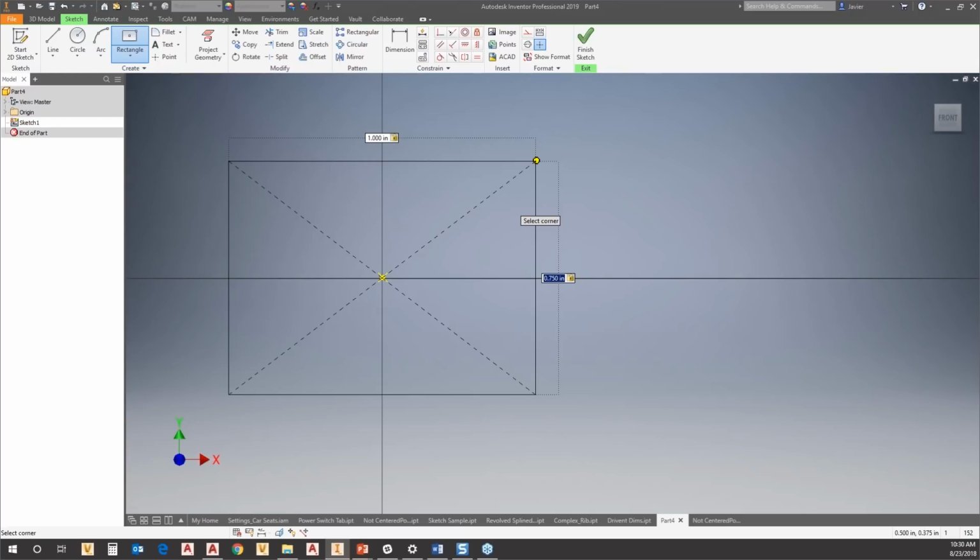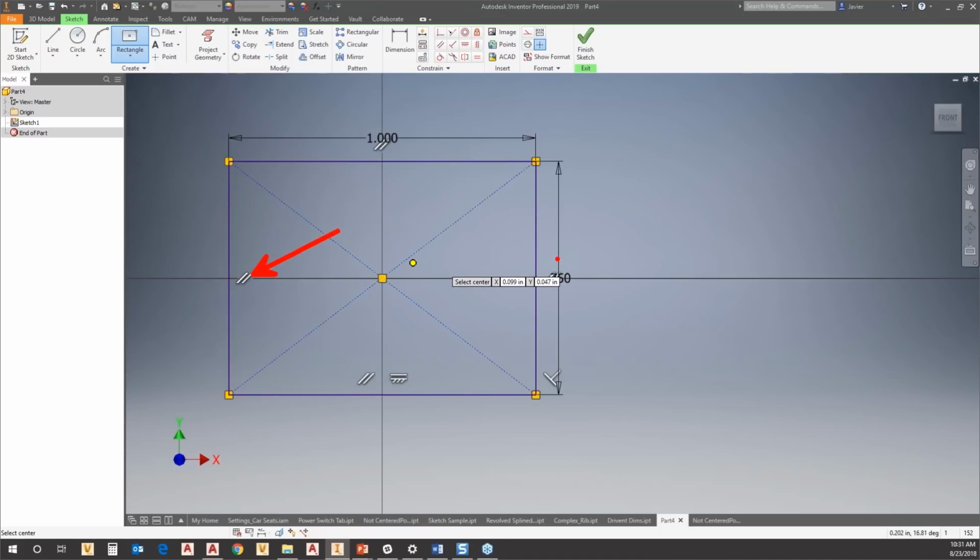In addition, right, we also use the rectangle command. So the rectangle command is going to automatically start putting in constraints relative to rectangles. So once I'm done, you can see some of those constraints. There's a parallel constraint that got added, right? You can see my glyphs are a little bit larger because of that annotation scale setting. There's a horizontal constraint being added. Every yellow dot means there's a coincident constraint. So this is fully constrained with one command.